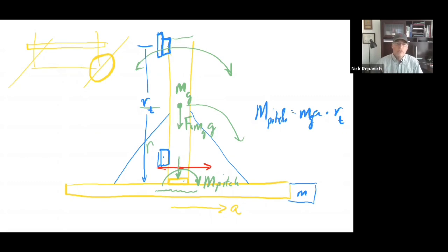So every single axis that you dream up or draw is going to have a different set of things. There's not one universal way of how you do it. You have to look at the sketch and think about each axis, and when you put that axis in motion, what kind of forces and what kind of moments does it have? You have static ones and you have dynamic ones. Static comes from regular G, and dynamic comes from the acceleration profile that you plan to put on it.